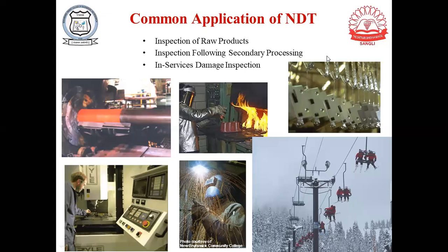Second thing is maybe in welding processes. Actually, non-destructive tests are widely used in welding processes. In case of welding processes, after welding, whether the components have properly joined or not, you can check by applying non-destructive testing on the welded parts. On that welded section, you can carry out any non-destructive testing, maybe x-ray testing or maybe dye penetrant testing. Out of these five non-destructive tests, you can carry out a test on that welded part, and you will easily understand if there is any crack or defect in the welded part or not. So in these kinds of secondary processing, you can also use non-destructive testing.